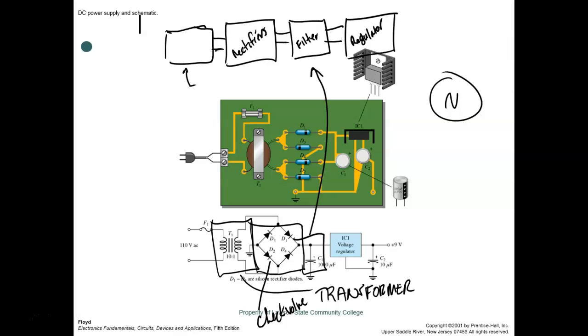So that's true on these power supplies. When I showed y'all last class, when I put another resistor across that thing, the ripple voltage went up, right? Which caused the output voltage to go down. So if I didn't have a regulator inside these trainers, every time you hooked up a load, you'd measure the voltage before you hooked the circuit up, and as soon as you hooked the circuit up, the voltage wouldn't be the same anymore, it'd be lower. Because if there's not a regulator to maintain a constant output, the voltage would vary with load. So that's what the regulators do.